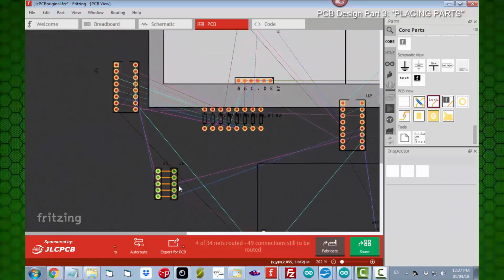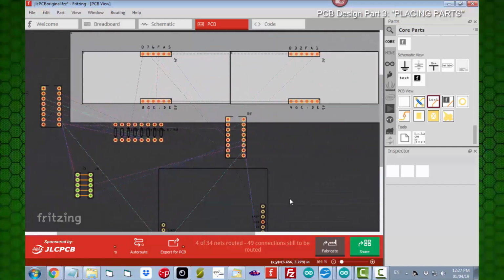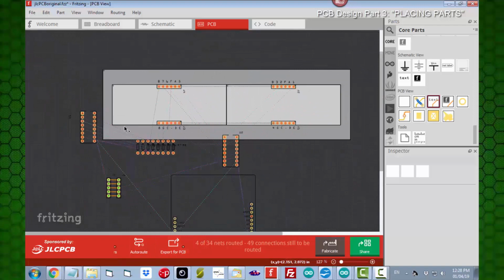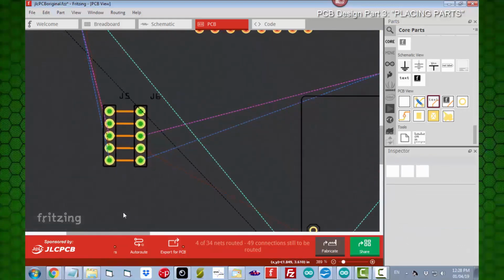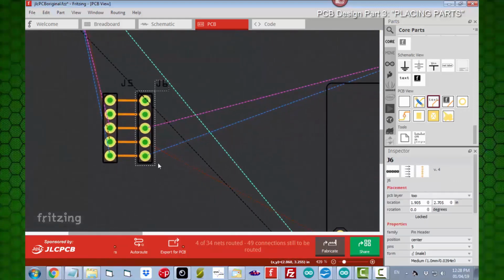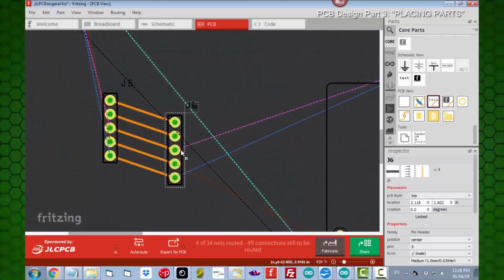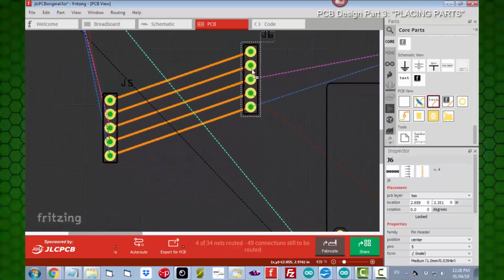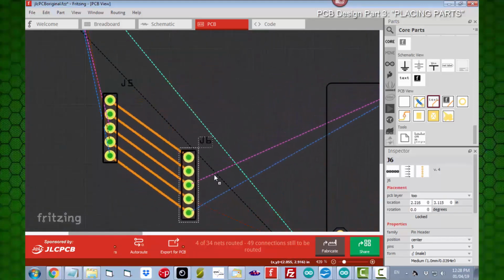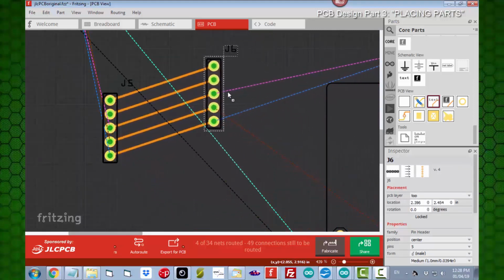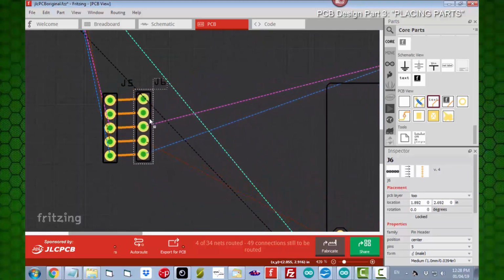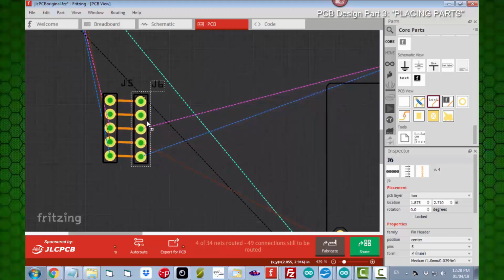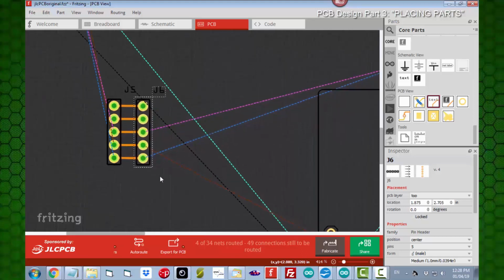These will actually end up on opposite ends of our printed circuit board when we're done. One will be over here, one will be over there, and we can move them around. And you go like, well, what happens if you start moving things around after you put the traces on? And this is really cool. You see, we can move it all over the board. The traces will follow along with us, just as the rat's nest wires did. So that'll work out pretty good for us. We'll just leave that there for now.